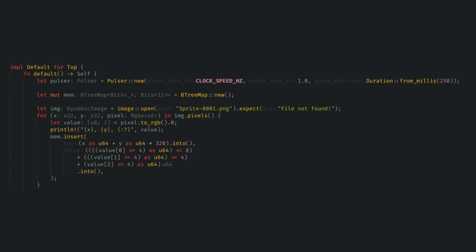Next up was displaying an actual image. I grabbed a quick crate that let me get the pixels out of a PNG, and I set up my RAM with the pixel contents. Then I wired up the pixel coordinates to the read address and the data to the colors and just kinda hoped my image would work.